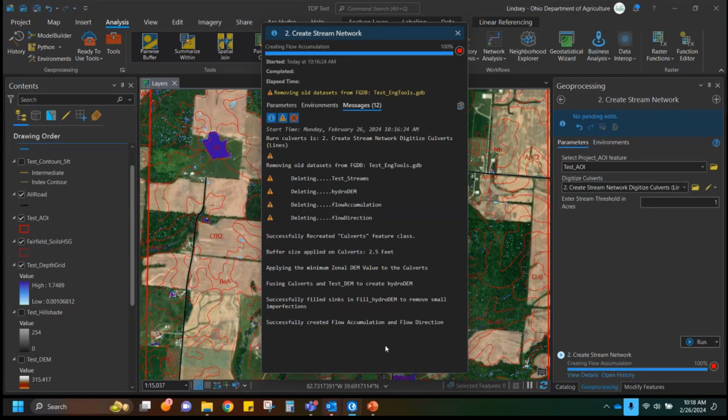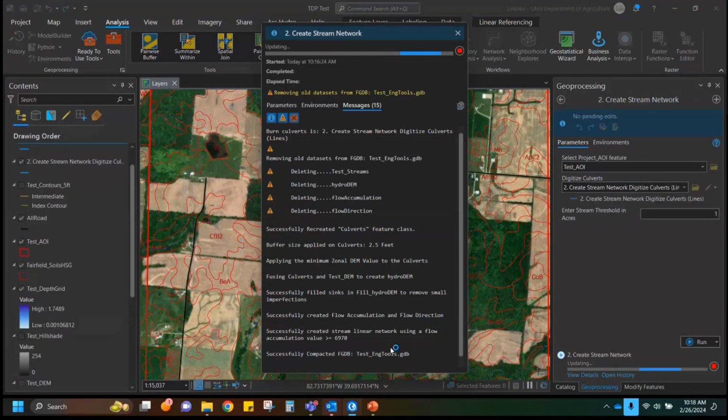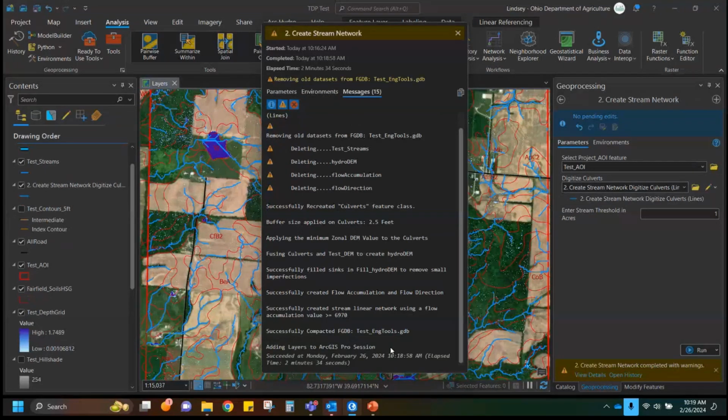We have a question from Dylan. He said, I assume the data from ODOT's TIMS site for items like the culvert and bridge inventory, that data from the websites is compatible with ArcPro the same as ArcGIS? Yes, it should be. I believe those are just shape files. And I think those are mostly on state routes, if I remember correctly. So like your township and your county roads might not have any data on those ones, but that is helpful if you have nothing. So it should work in ArcPro just like it did in ArcMap.